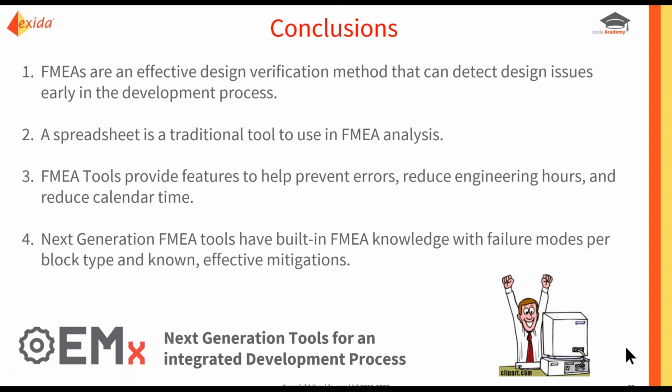No, it is not. In fact, I don't recommend it at all. I recommend FMEDA instead, unless you don't care about failure rate, failure mode, quantitative predictions. In any case, you get a lot of benefit. It's very time consuming going down to the component level. You get a lot of benefit at the architecture design level.